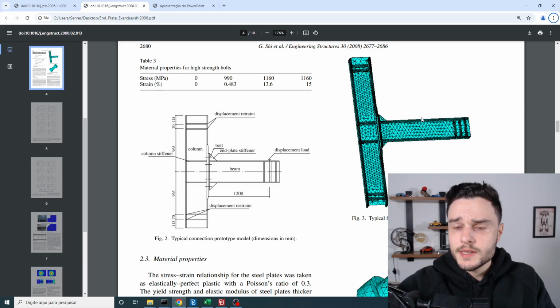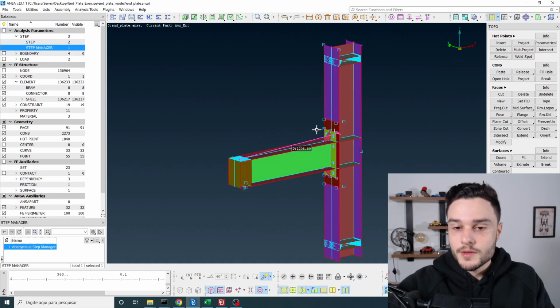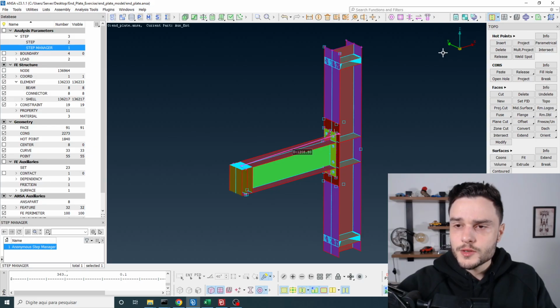When we have the symmetry condition being used, in the symmetry plane that is not visible here in this image, he needs to apply some boundary conditions such as fixing displacement in the y direction. Let's look at what this direction is. You see this coordinate system here, the y direction is this direction here. The y direction would be in the normal direction of the symmetry plane.